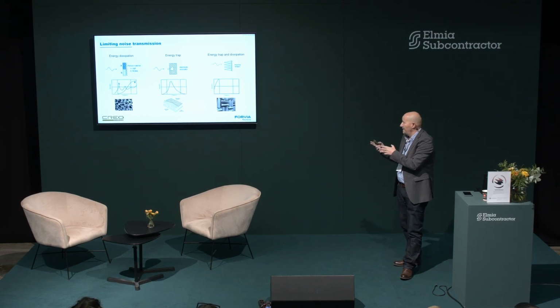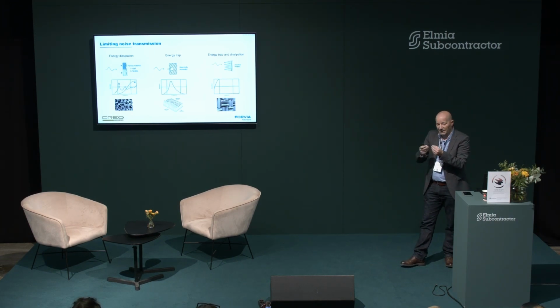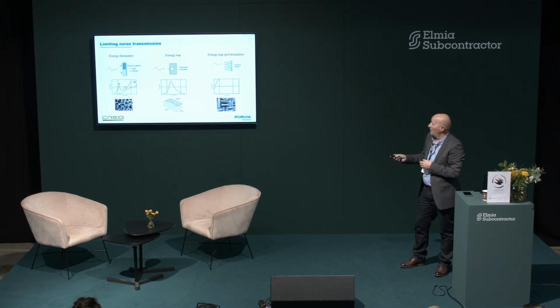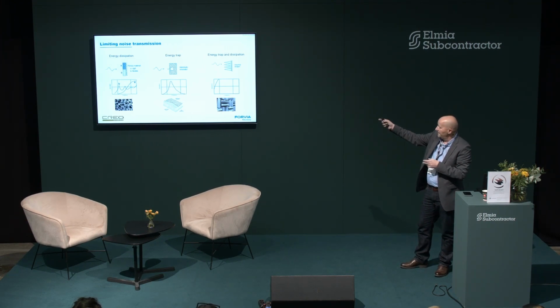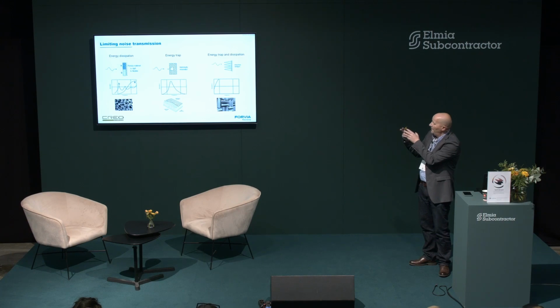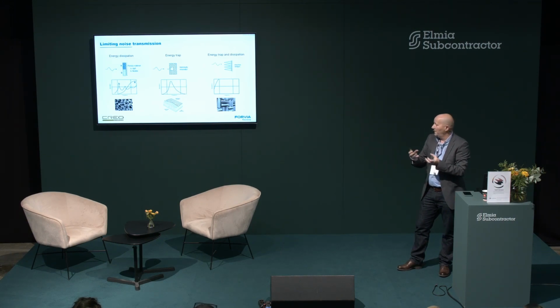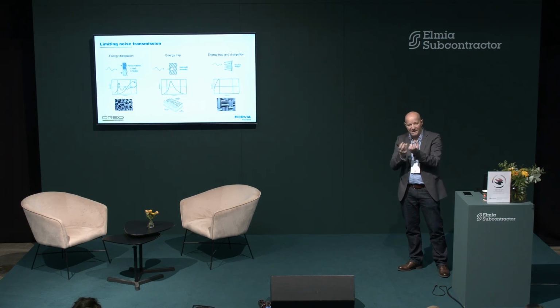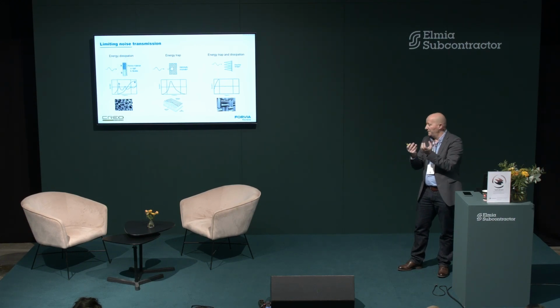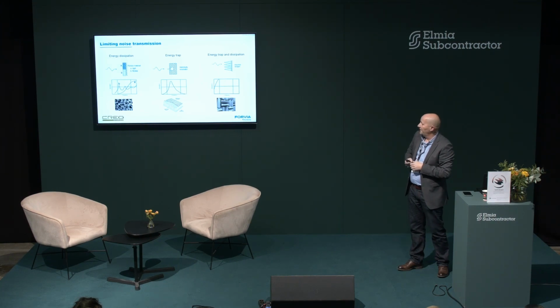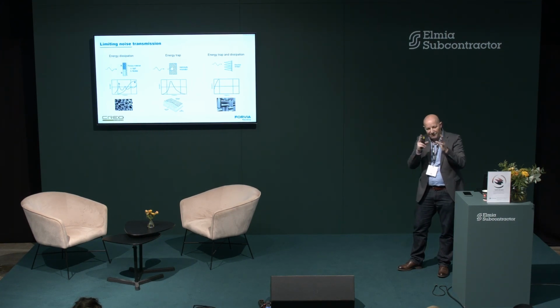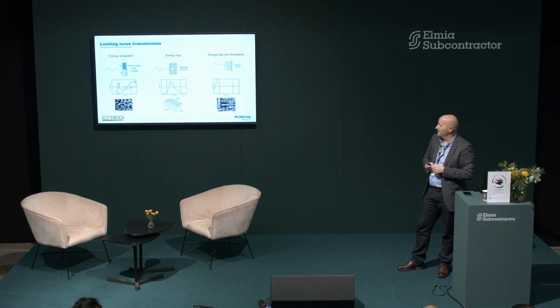Another process is to trap the energy in structures. So small, for example, cavity with a neck like that are so-called Helmholtz resonators, and this type of small cavity plays like a mass spring system, and this mass spring system can absorb energy, and usually these materials, you can tune them to a certain frequency when you have frequencies that are coming up, where you can increase the absorption.